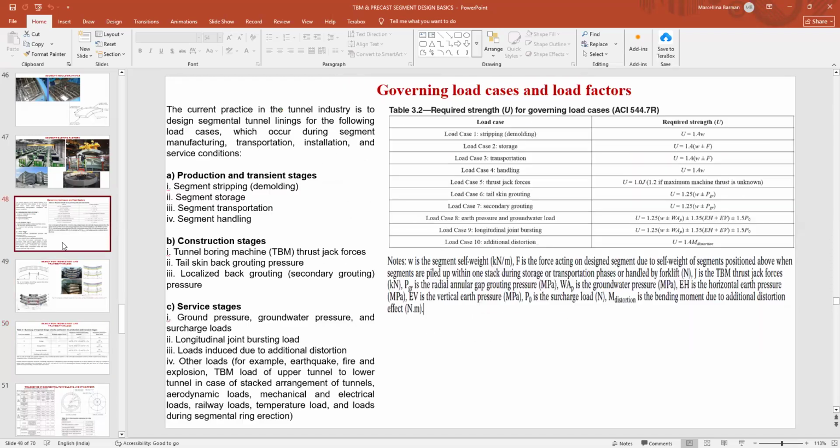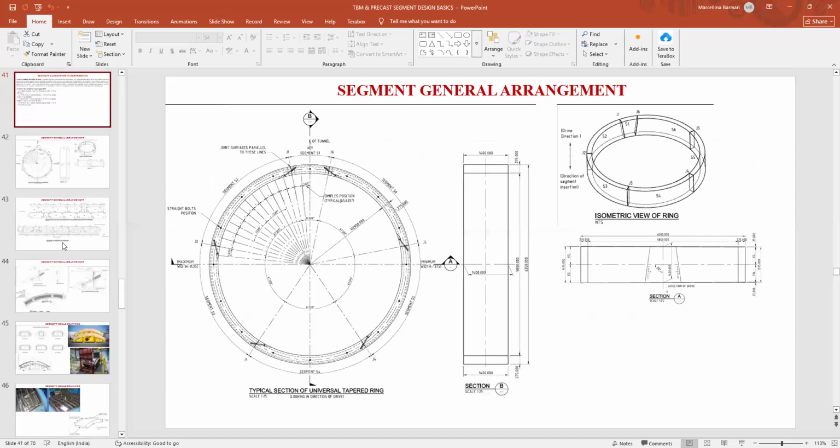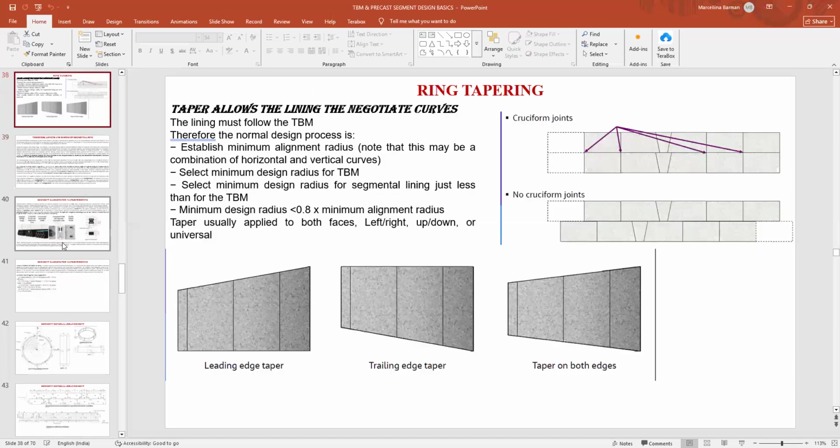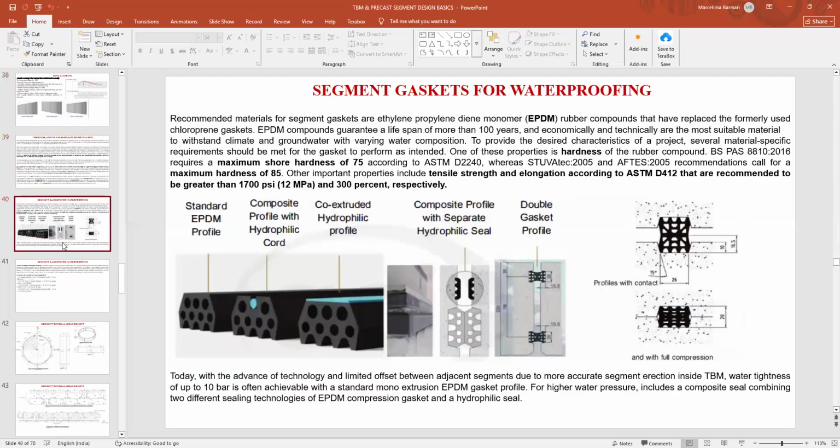So that is why the number of pieces has been defined by the different design guidelines, or you can take the different country codes as per their experience. It's not that I can't make it as a 3 plus 1. You can make it as a 3 plus 2, but what happens is that for making that 5.5 meter circle, your piece length will also increase, or your key piece will also increase.